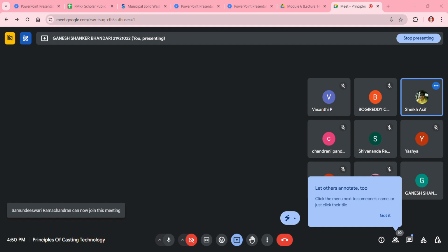So it has to be around, I think it will not be 0.33 hour per trip, it will be 0.033 hour per trip, because 0.33 hour per trip is like 33 minutes. You are not going to take that much time to pick up that container from that site. It will take hardly 3 to 4 minutes only. So there is some mistake in this container pickup time, that has to be 0.033 hour per trip. You can easily calculate that according to that formula.